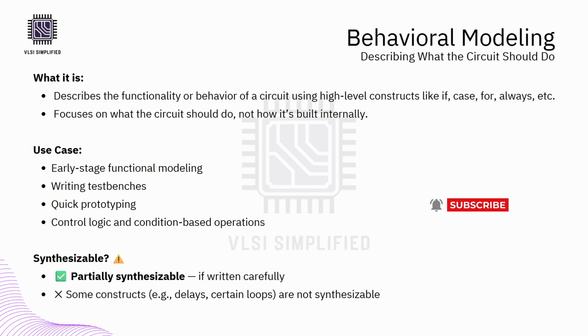However, not all behavioral code is synthesizable. Some constructs like delays or forever loops are simulation only. But if you write your behavioral logic properly, as you will see in the next slide, it can be synthesized into real hardware. Now let's take a look at how to model a simple AND gate using a behavioral approach.